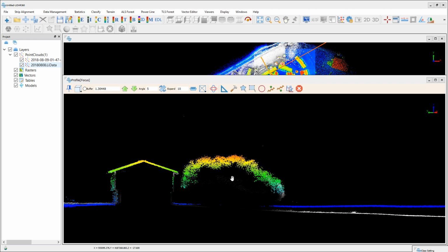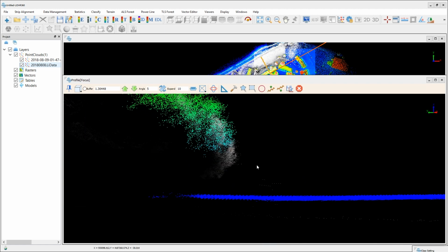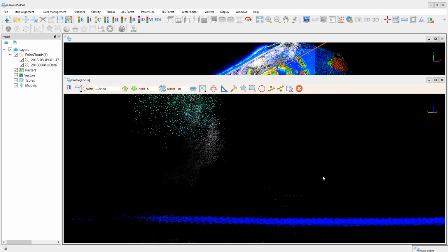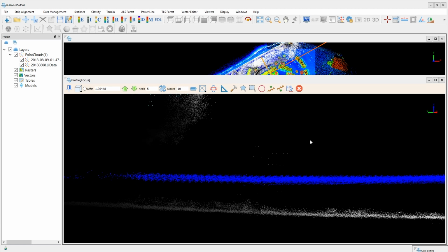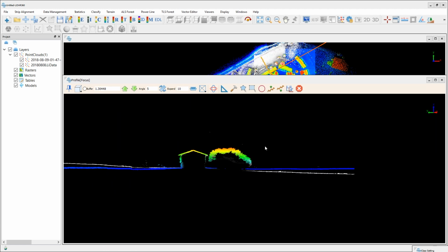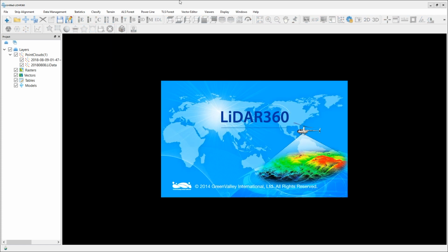You can also see here on this tree that the gray dots and the colored dots do not align very well. This makes me realize that while I did achieve good fit between matching point pairs for the sets I used, globally there's still a lot of error in the registration between the two data sets.